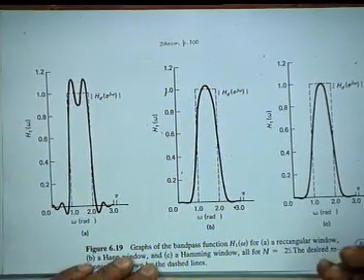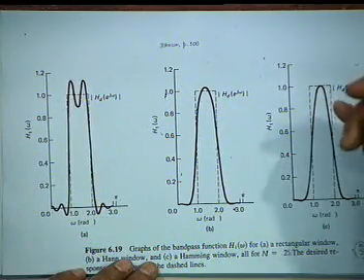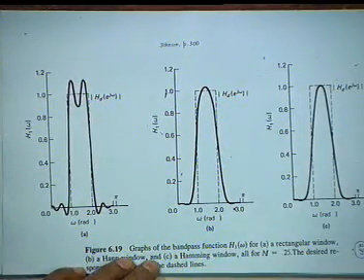Then the band pass with the same length, N equal to 25. Here the magnitudes have not been normalized, but you see Hamming, it's a coincidence. No, it is not a coincidence. When capital N increases, Hamming normalizes its maximum magnitude to 1.